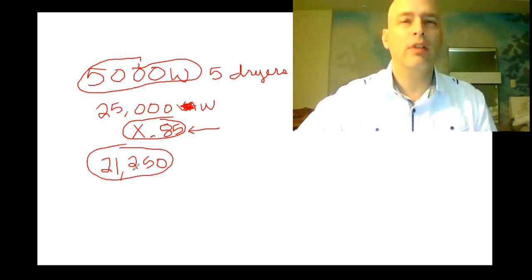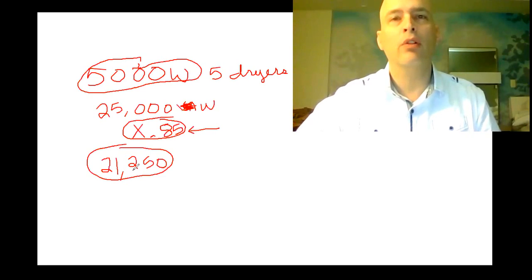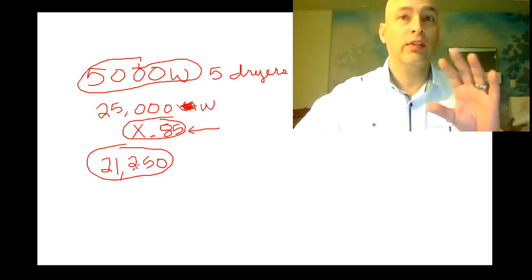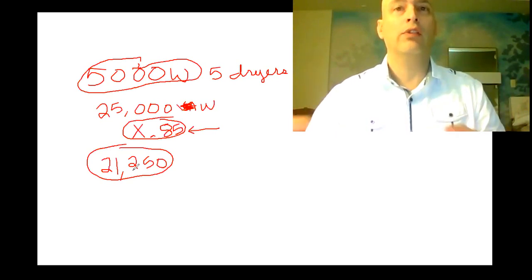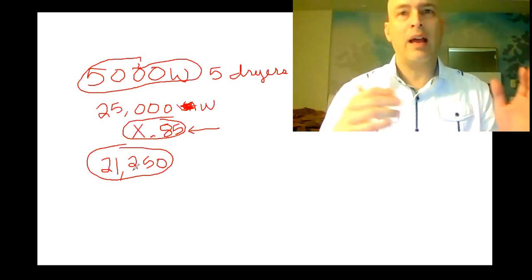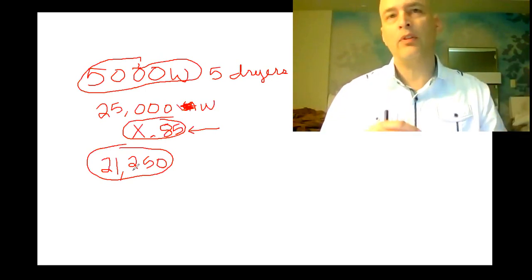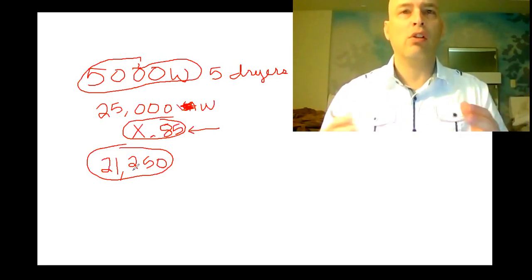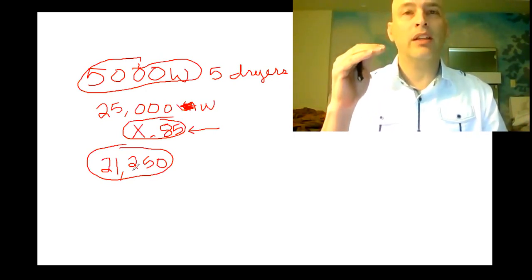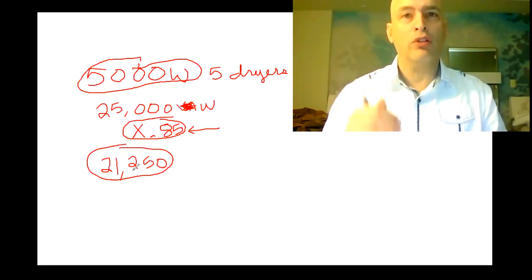And with dryers, if we have 1 or 2 of them, it might be that they're both running at the same time. But as we add more units to the same service with dryers, you would expect to see dryers in use at different times, different start times, different run times. So the diversification of the load lessens, and we don't worry about calculating the full 100% any longer. That's why you'll notice on this table it continues to get smaller as you go down.